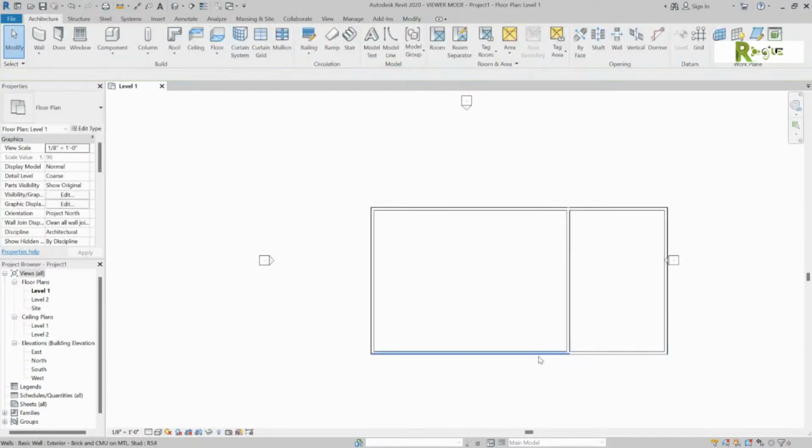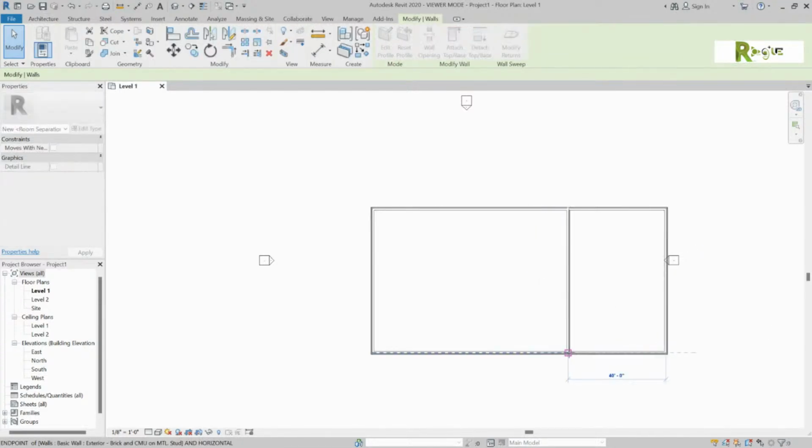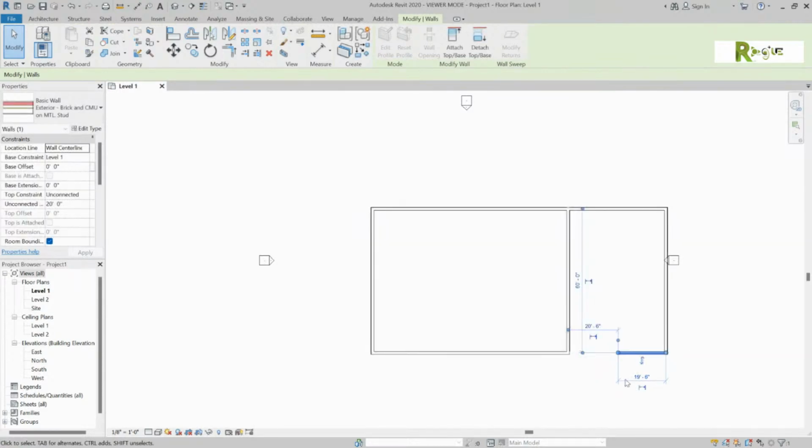Don't make it shrink to nothing. There you go. Just pull it away a little bit. Perfect. Now notice your temporary dimensions there. Well, for a garage, you really only need 22 feet deep. So change that 60 to a 22. Okay. All right. So you can see your overall building is pretty doggone big, but that's not a problem.